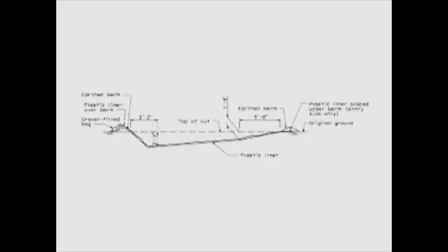Place the liner under the berm on the entry side of the below-grade facility. Then, place the remaining liner into the excavated area as well as over the earthen berm of the remaining 3 sides. The liner is then anchored with gravel-filled bags.